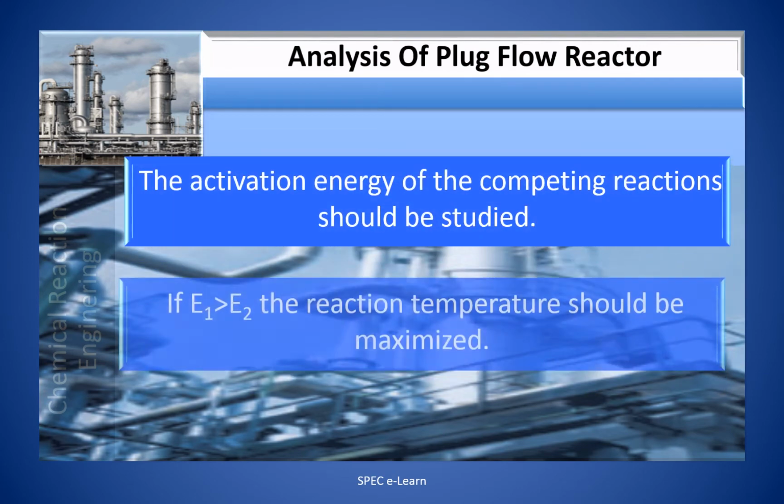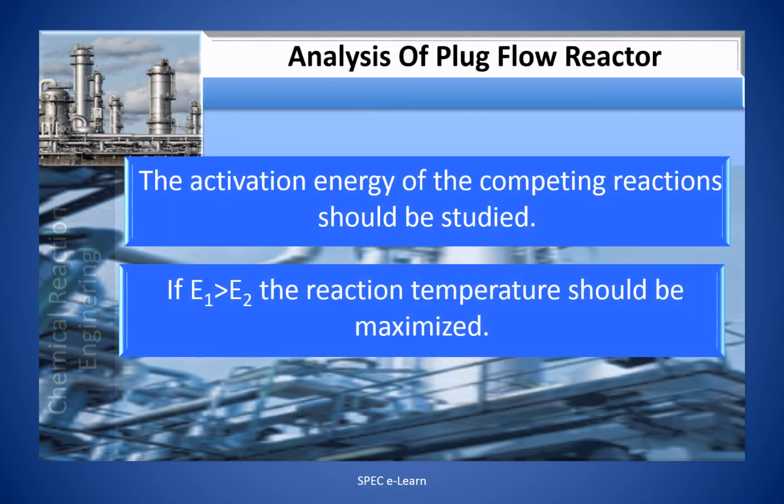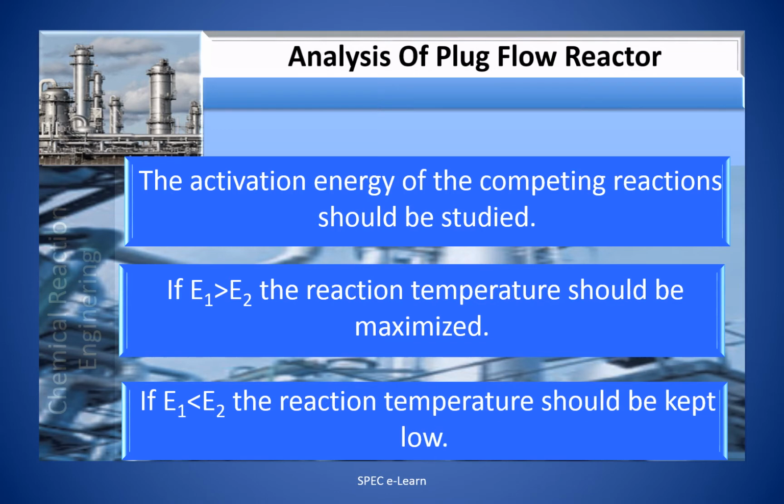The activation energy of the competing reactions should be studied. If E1, the activation energy of reaction 1, is greater than E2, the reaction temperature should be maximized. If the activation energy E1 is less than E2, the reaction temperature should be kept low.